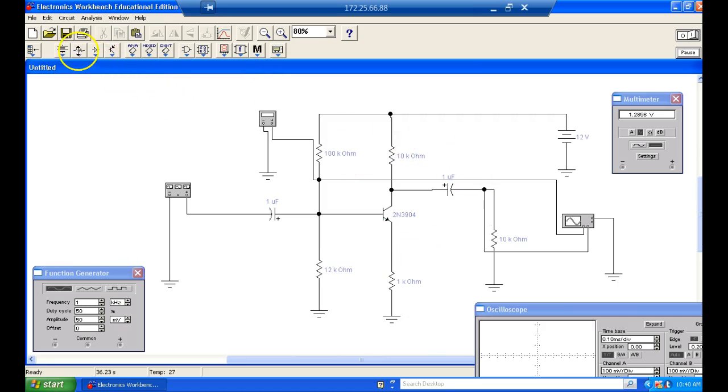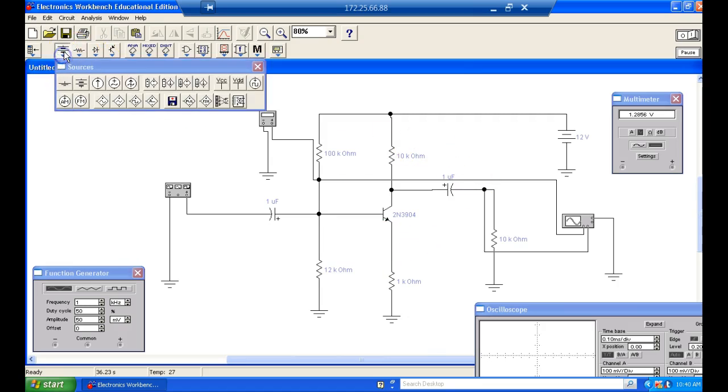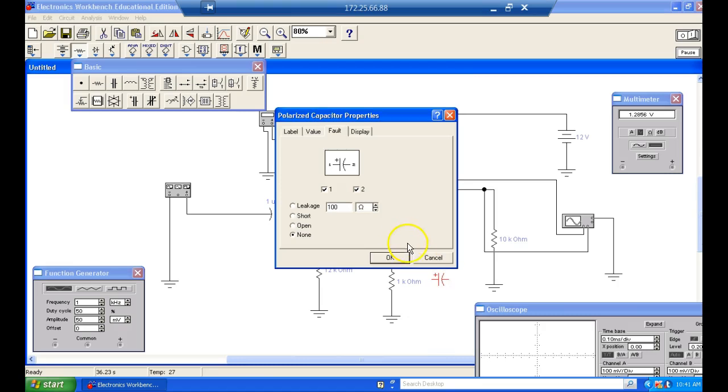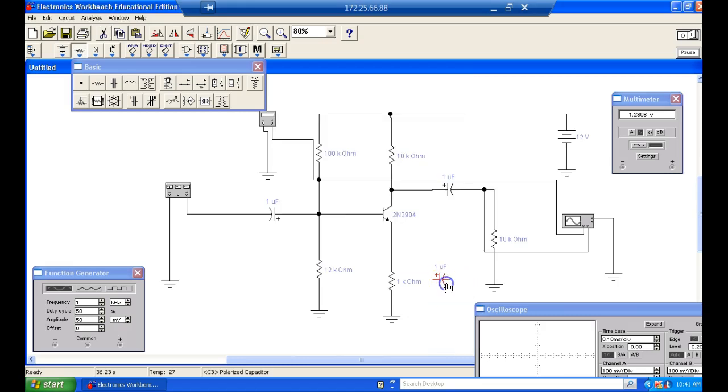There was one thing that we left off this, and this was, what do we need to do to increase the gain of this thing? Could do that, but another technique we have is to bypass this capacitor right here. And we call this a bypass capacitor.